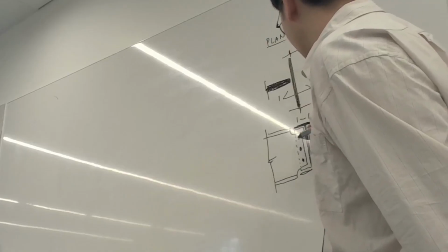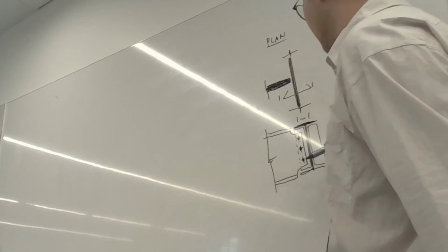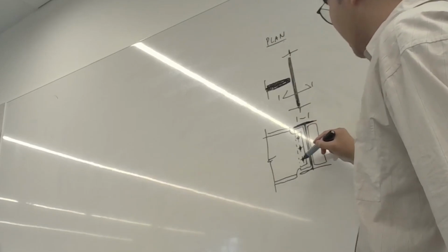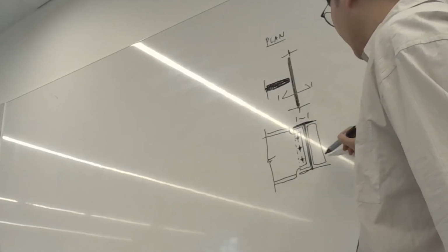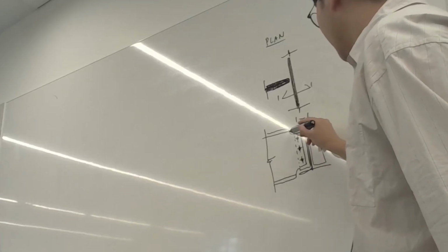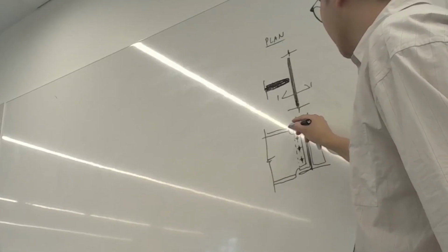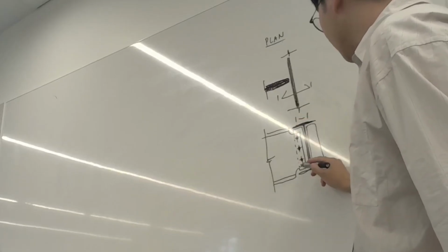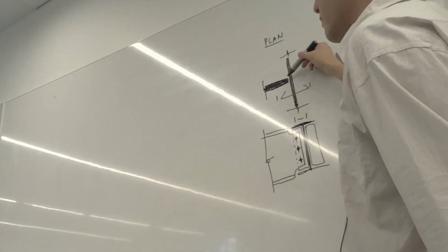How you draw bolts is a plus sign like that to indicate that they're bolts. And this dashed line indicates something's behind there, so that line represents the edge of the stiffener. And that fillet thing is your coping. We've removed a portion of the flange and a portion of the web there, so that these can attach nicely. So that would be a pin connection, there to there.